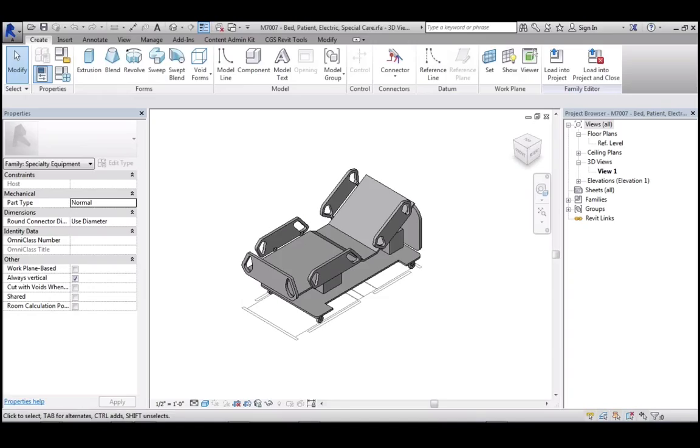Right. And the objects that we use in SEPS, those families in the templates, are kept quite simple. This is probably one of the most elaborate objects with those wheels, but in general we kept them quite simple, so you don't get very large file sizes. You can try that yourself. If you create a simple bounding box block of a family, and you create an object like this, the file size is almost the same. There's just overhead in Revit. If you create any kind of object, it has a certain minimal size, and that's what you have in your file.